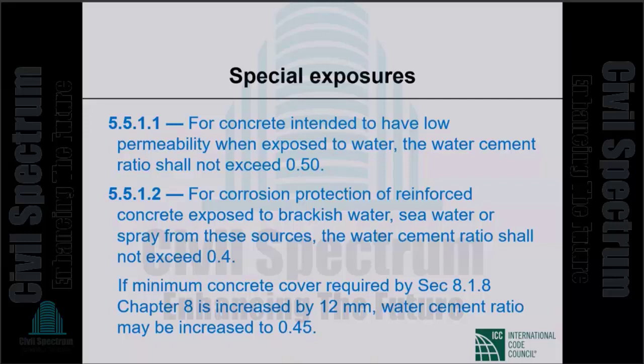Shall not exceed 0.5. That is a pretty generous number. It is not a very tight restriction. So that's watertight concrete. For corrosion protection of reinforced concrete exposed to brackish water, that means water that stands still, seawater, or spray from these sources, the water cement ratio shall not exceed 0.4. Now it is much tighter.